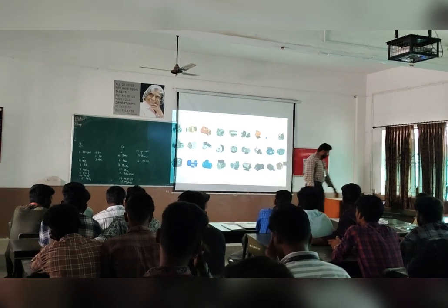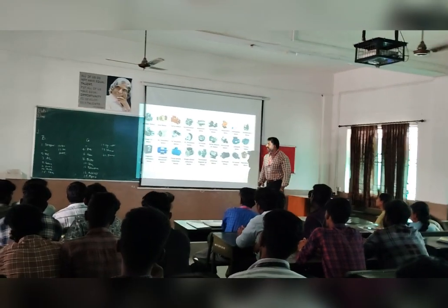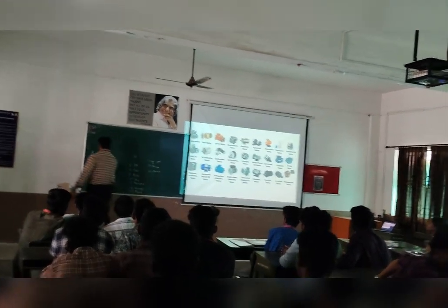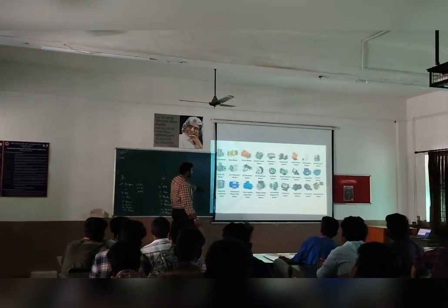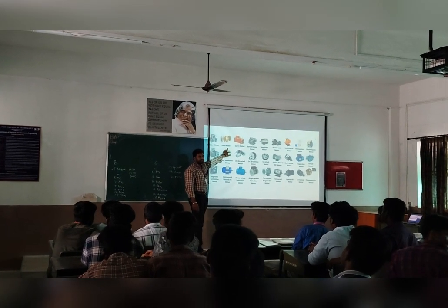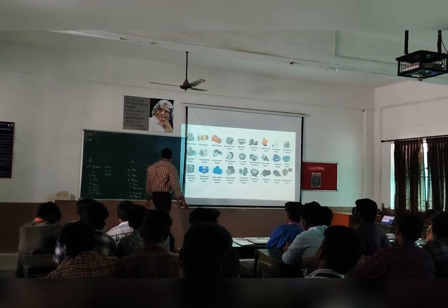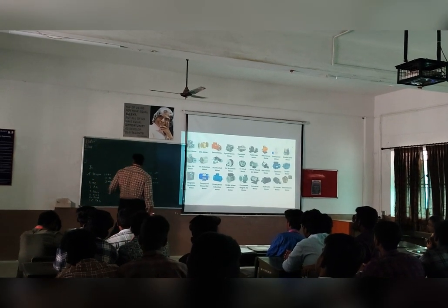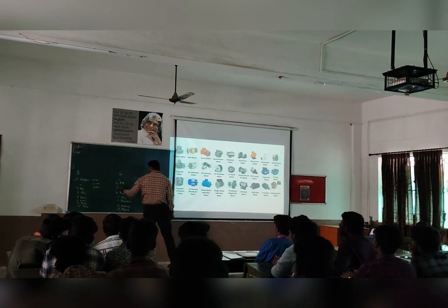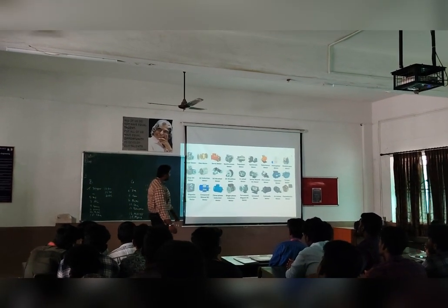And also we have two things, for example driver and driven. If we use an odd number of gears, the direction of the speed will be the same, and an even number of gears will give the opposite direction. In the external spur gear, the gears of two shafts mesh externally with each other, as shown here. The larger of the two wheels is called the spur wheel, and the smaller wheel is called the pinion.